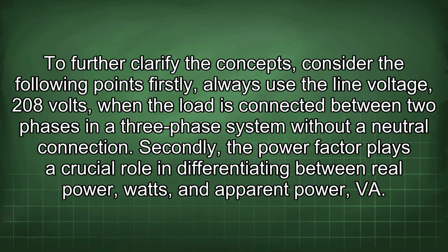To further clarify the concepts, consider the following points. Firstly, always use the line voltage, 208 volts, when the load is connected between two phases in a three-phase system without a neutral connection.